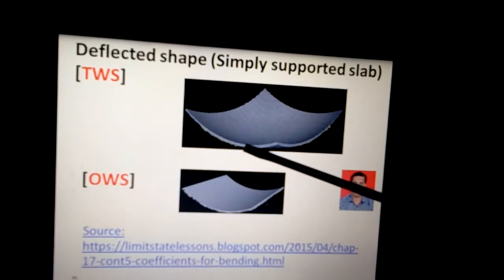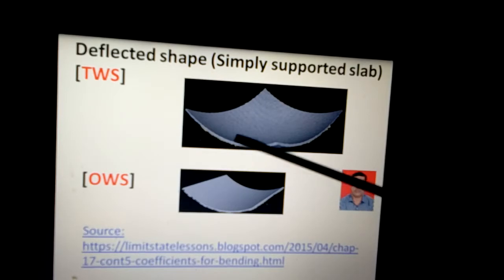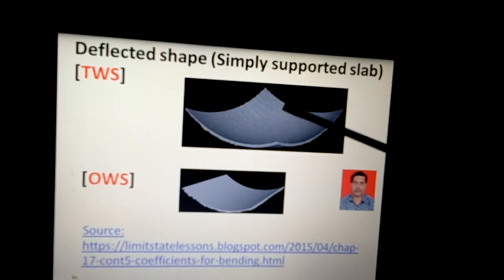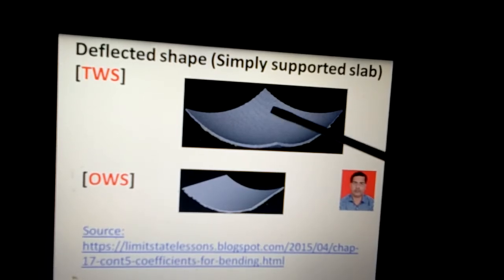So with this, if we further think about the influence of deflection in the slab and the bending characteristics. If we take a simply supported slab, a slab simply resting on the four walls, then under the influence of the external load, the slab would bend like this. The shorter span is bending and the longer span is also bending here, and this bending takes place simultaneously, and because of this a slab is deflected as it is seen in the image.